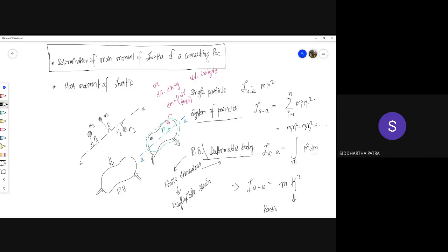This is not the definition of mass moment of inertia, but the definition of radius of gyration. Basically there could be two objects, one which looks like this cylinder, which has mass, but the mass is not much dispersed from the axis, whereas I can think of another cylinder with the same mass possibly, but the mass being distributed away from the axis.